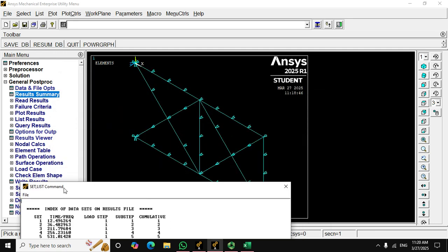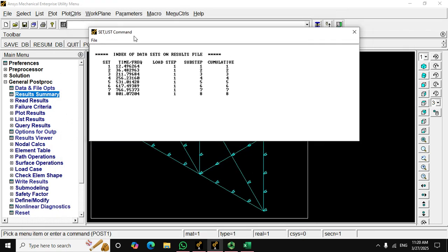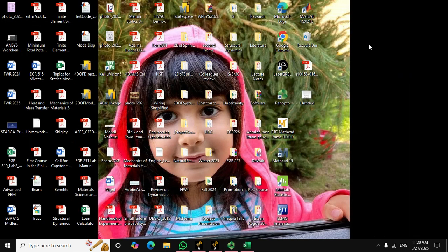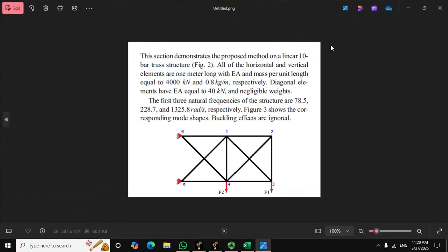The reason is that if you constrain this model to 2D, the degrees of freedom I have here is basically just 8, because I constrained node 6 and node 5, right? So no degrees of freedom there. But points 1, 2, 3, 4 are the only nodes that are free to move.